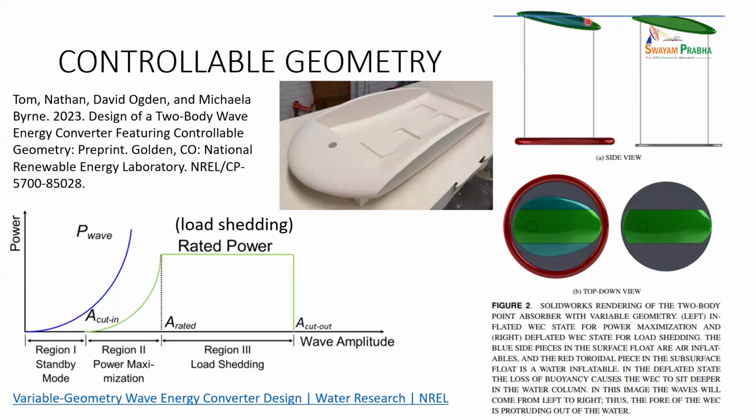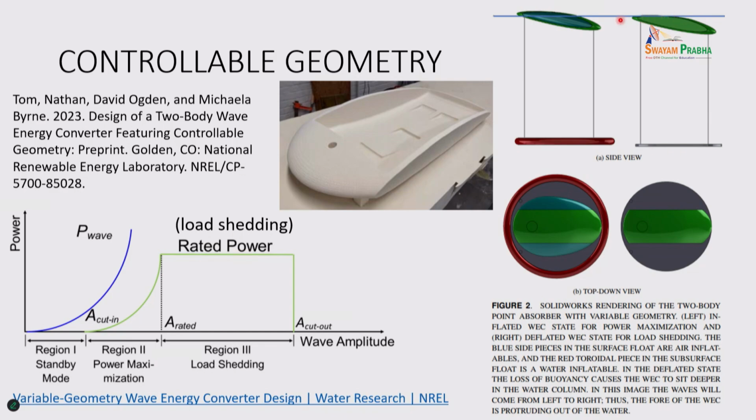What's that water line? You remember, hydrostatic stiffness, right? If you have a water line like that with a larger area, then you have higher stiffness. Or you deflate, and once you deflate, you have a smaller water line area, then you have smaller stiffness.